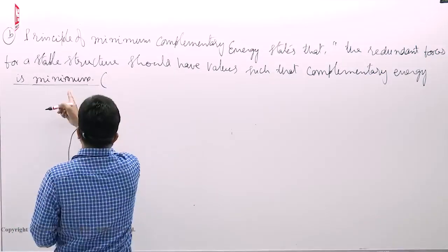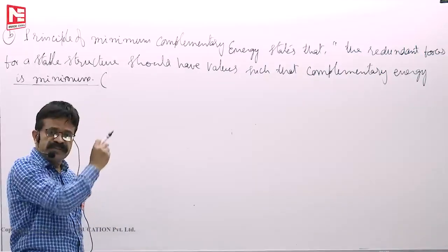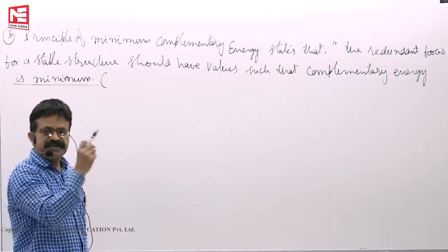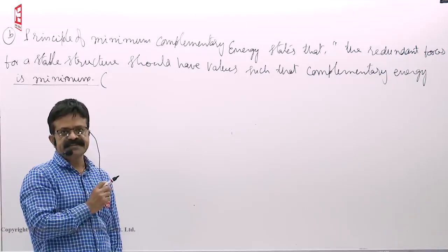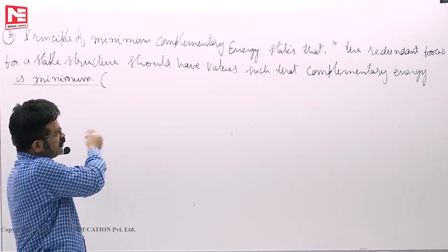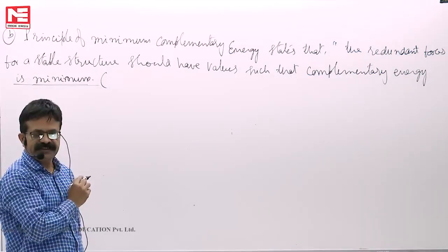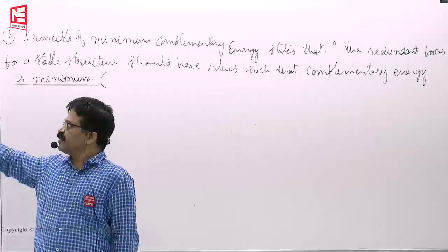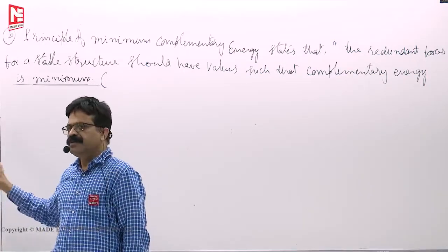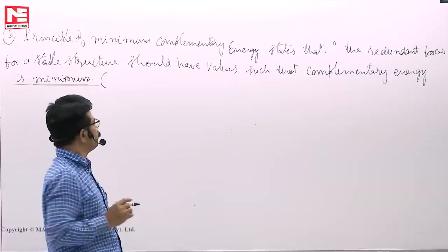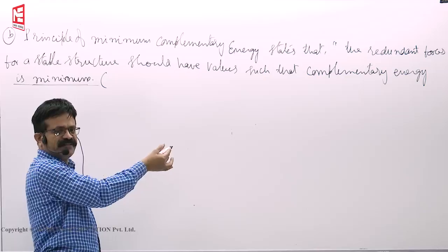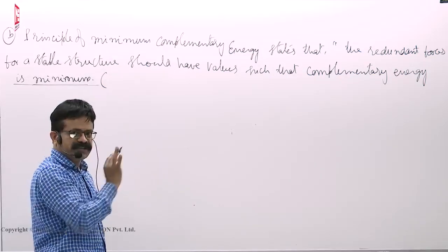But this is provided there are no displacements at the redundant reaction locations. That means when you are dealing with support reactions, etc., where there are no displacements, the principle of complementary energy will come into the picture. Your Crotty-Engesser theorem becomes the principle of minimum complementary energy, a particular case where dou U by dou x is equal to 0.